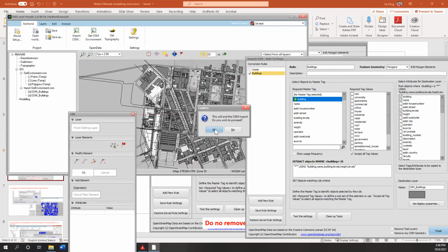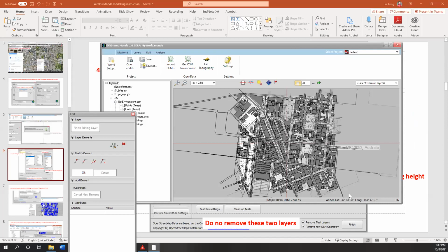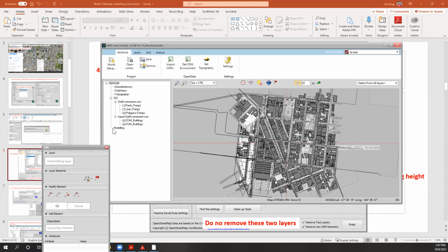Then you will have the OpenStreetMap database. For example, our site is the center of the map. Say you input a reflectivity of concrete and add it in the system database. The next time, your model will load the concrete profile from the system database, and you may not be aware of that. If you want to check what is included by default, you can go to layers and see the building layers appearing under the GIS category.